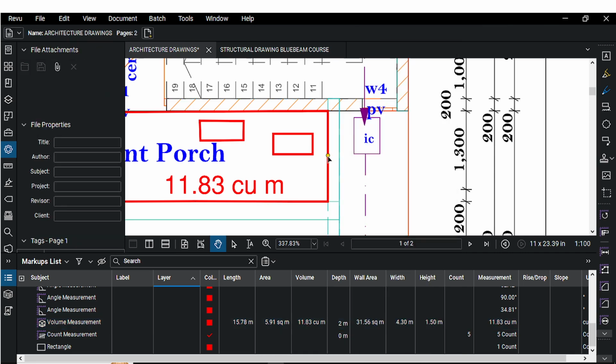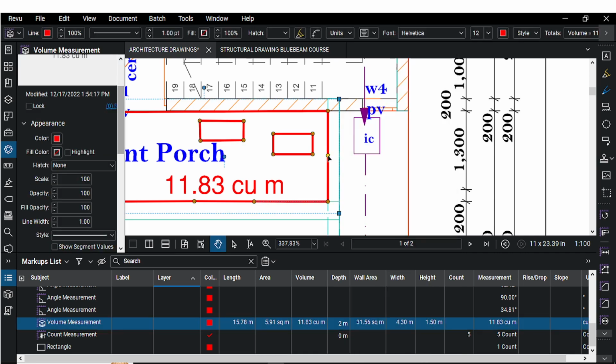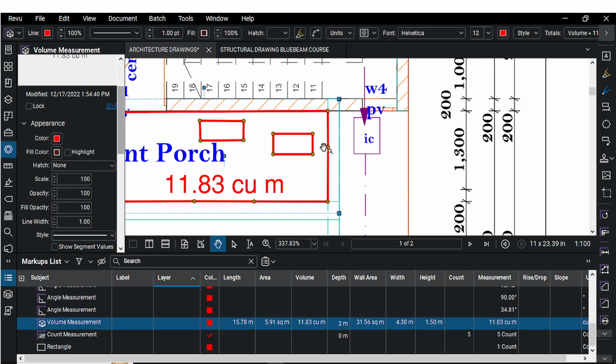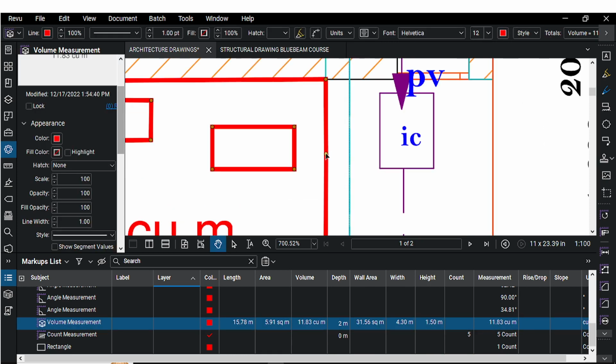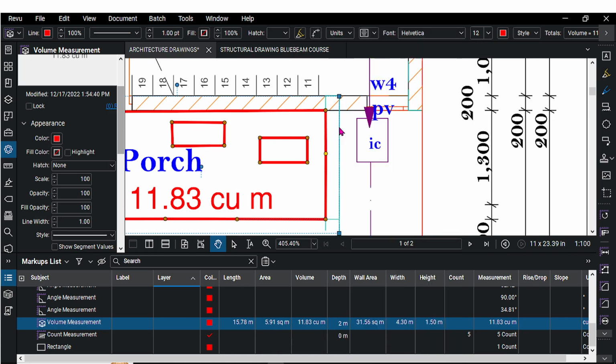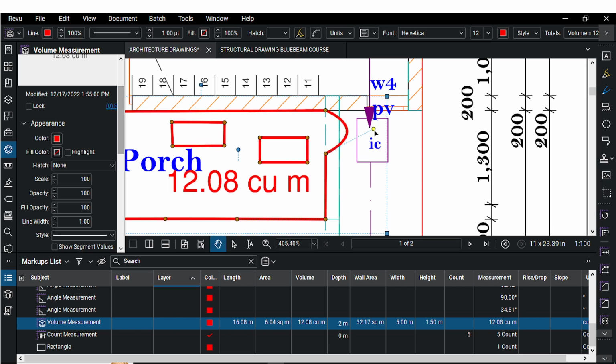For you to be able to create a curve, you need to be at this point. You need to click at this particular control point. I need to right click there and then click on convert to curve. Now in this case, it is going to produce another control point, so we can use it to convert to curve like that. I hope that is clear.